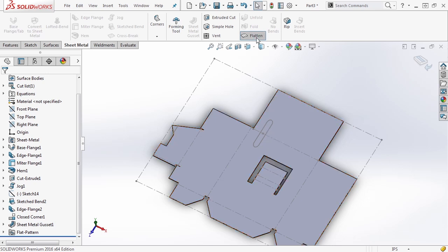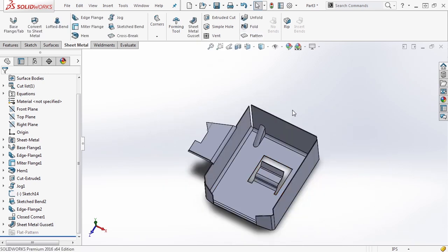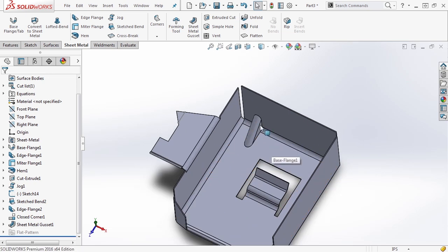For whatever reason, SolidWorks does not turn that option on by default, so if you're using sheet metal gussets, make sure that you go in there, turn that on, and understand what it's doing for you. As I said, there are plenty of other tools inside of the sheet metal suite that you can add to your design to make them that much better.